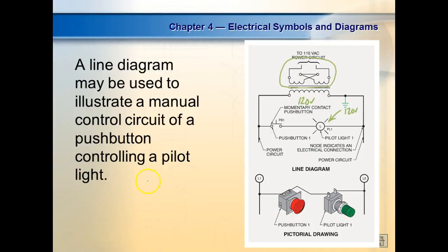So what we have on this: if I wire DC power sources, we got 2 ways we can hook up these power sources. Actually, we got multiple ways, but the 2 most predominant ways are that we can hook them up in parallel or we can hook them up in series. Normally when we hook them up in series, we hook them up in what we call series aiding power sources.